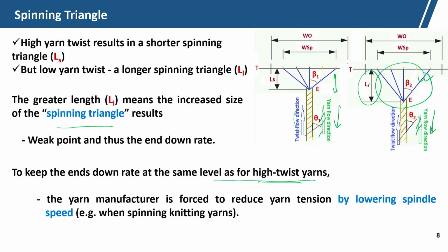So, there will be breakage. So, for lower twist we have to reduce the spindle speed.